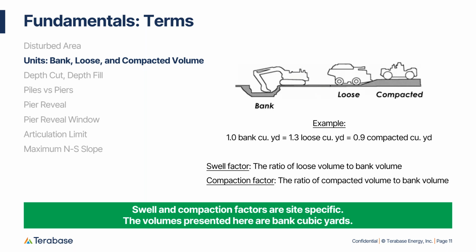So it's imperative to include these requests when you're scoping your geotechnical report. You ask the geotech for some recommendations on what they think these might be, because it does have an impact on your cost. You can have swell factors of 1.6. That makes a big difference when you're trying to move that soil around the site. So we want to be clear that our software is estimating bank cubic yards, and we want to highlight that earthwork assessments can be nuanced when you're seeking balanced cut and fill. Next slide, please.